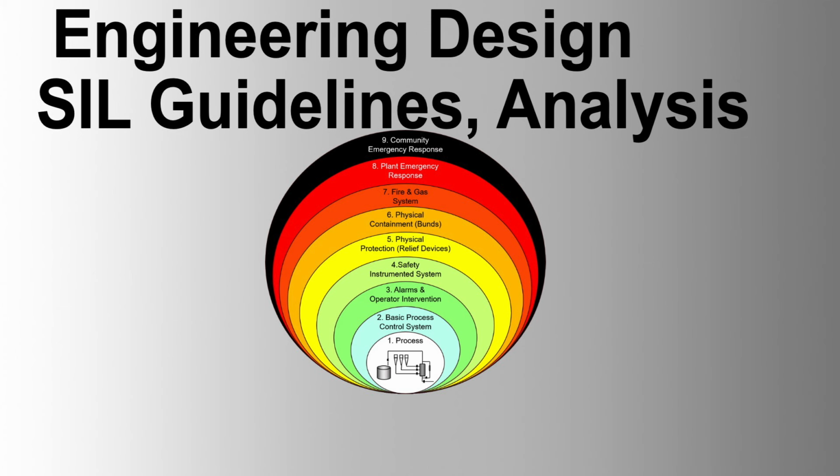2. Top event identification. Define the top event for SIL determination, representing the probability of the SIS failing on demand for a given safety function. Multiple safety functions may require separate fault trees. 3. Construction of the fault tree.